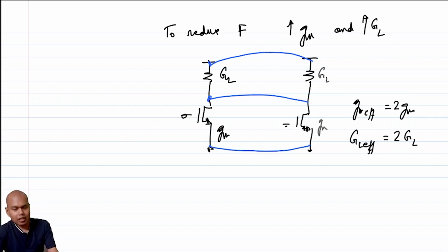So again, just like signal to noise ratio that we had talked about earlier, in order to reduce the noise factor, your handle is still the same. You essentially copy the circuit multiple times and put them together node by node in parallel. What is the trade-off? Obviously, the trade-off is the power consumption, because if one of the stacks was consuming I current, 2 stacks will consume twice the I, right?